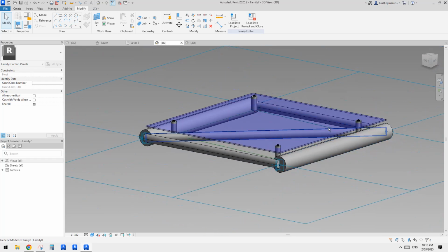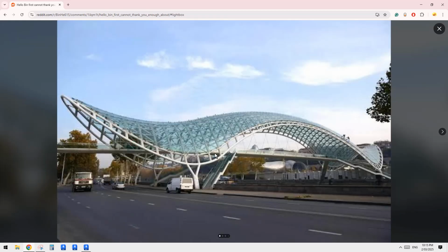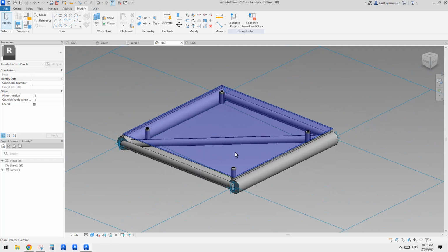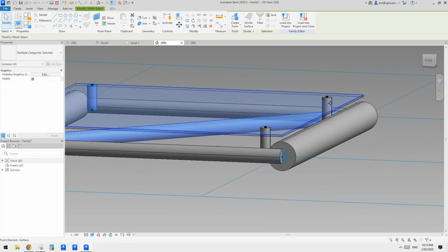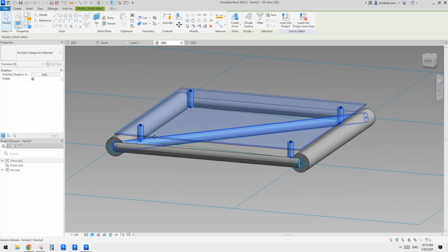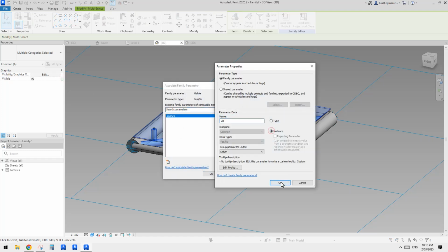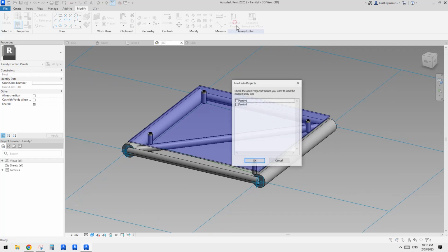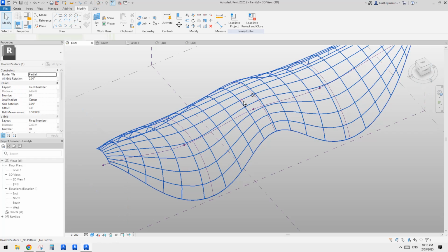family. So I think this is good, and before we load this one, I noticed that see here, there's someplace there's no glazing, and also there's no diagonal frame, so we can actually select all these glazing and fixing and also the diagonal one, and create a parameter. I'll just call it this and maybe instance, and now we can load this one into the project, into the conceptual mass. Okay, so let's go to the 3D view, select this.